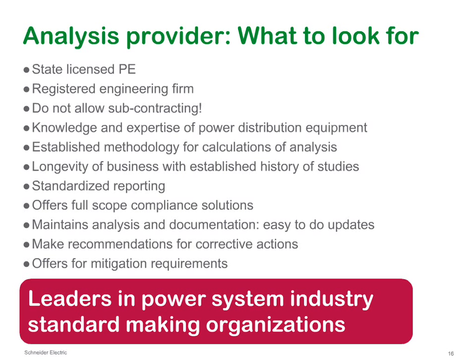So you could demand standardized reporting, national coverage of the company if you are of the kind of corporation who has multiple facilities. And finally, and most importantly, make sure that the supplier makes recommendations for corrective actions to reduce arc flash energies where the energies are high enough that they make safe performance of work on that equipment impossible. So look for those factors.